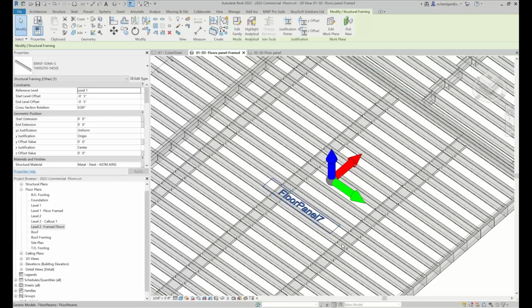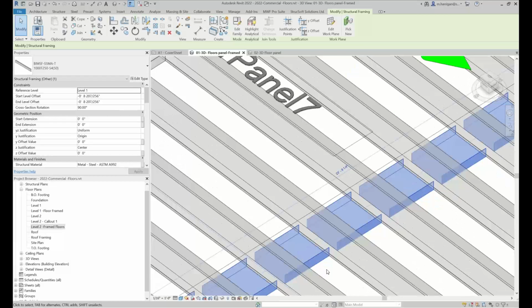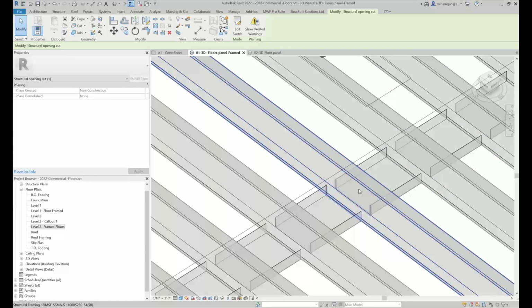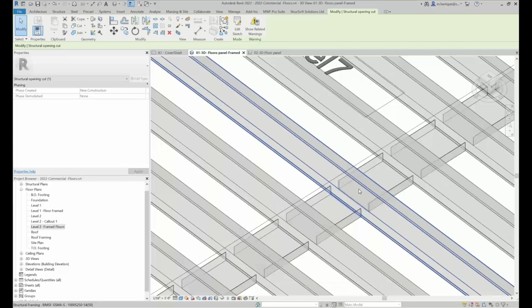Next one is the notching. So you can see that because it is set to my rectangle hole, I have created a continuous member and it is cut where the joist is. If I change the rectangle hole to something smaller, I can maybe have the member and then just cut the portion here. Also, if I zoom back in there, this is our rectangle hole. Again, this is just for the notching. However, we can create hole types that are just rectangle in your joist also.